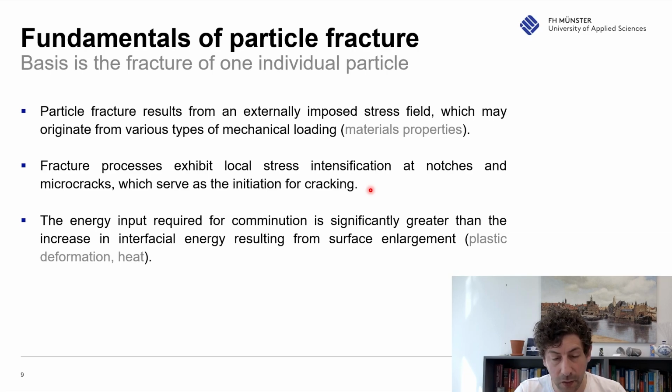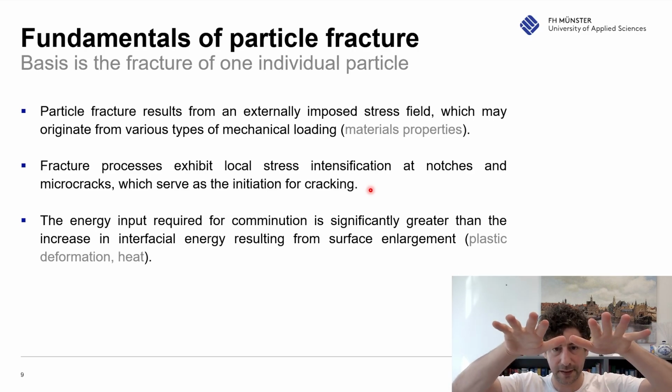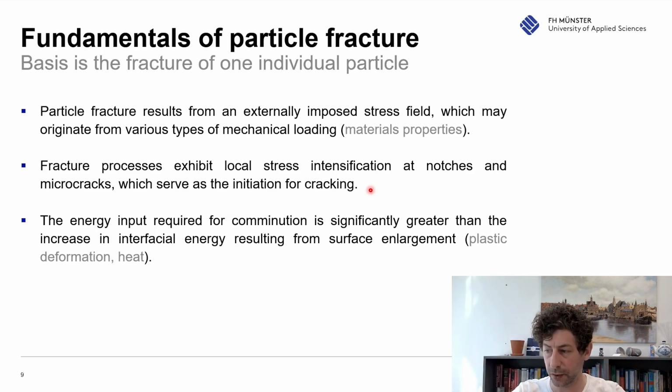And this means around these notches, the stress lines are densified. So the stress is increasing. If I have a perfect material without any failure, it's very strong because the stress lines can go equally through it. But if you have somewhere a notch, a crack or something, the stress lines have to go around, they intensify, and the cracking starts there. And this is how particles crack.